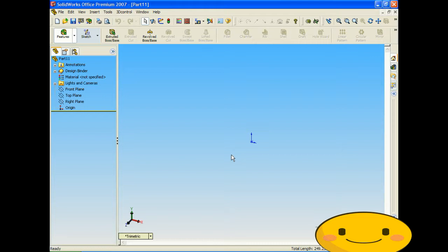And what a construction line does in a sketch is you're able to make references off of it to constrain the other remaining sketches that aren't construction lines. And then when you go to extrude or create a feature from it, the construction lines are kind of like hidden, but they're still constraining the original sketch.